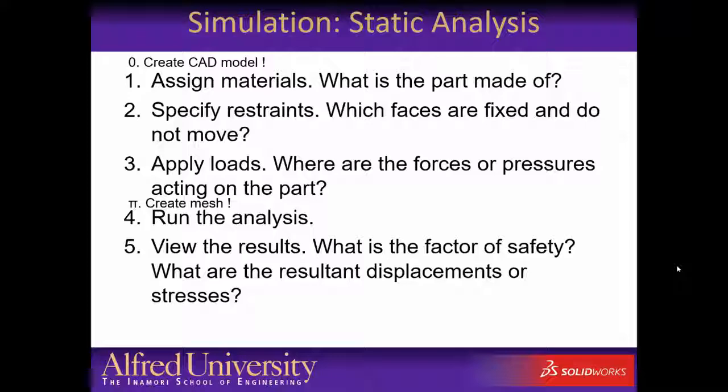Once the material has been assigned, we must specify restraints. You must ask what faces are fixed and do not move. We not only can restrain faces, we can also restrain edges or even individual points, and there are different ways in which we can restrain the motion of any given one of these entities.